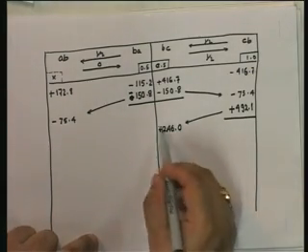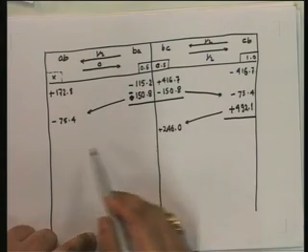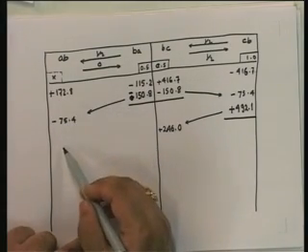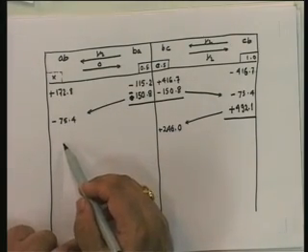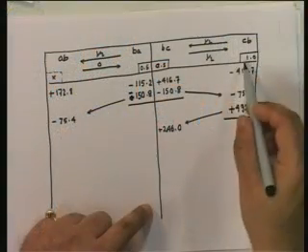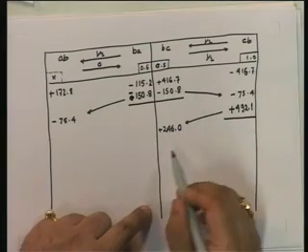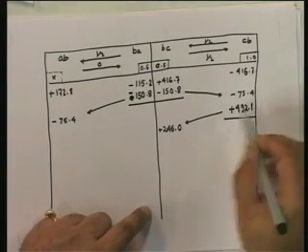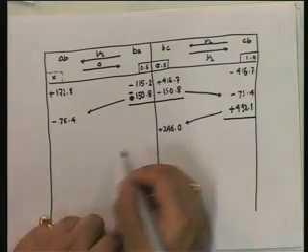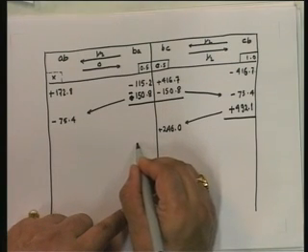Okay. Now note that here there is no question of unbalanced moment because this is a fixed end. When you have a fixed end, you do not require any release. You cannot have an unbalanced moment here. Now as soon as you release this, you've got this. So now you need to distribute this. So distribute it half, half.